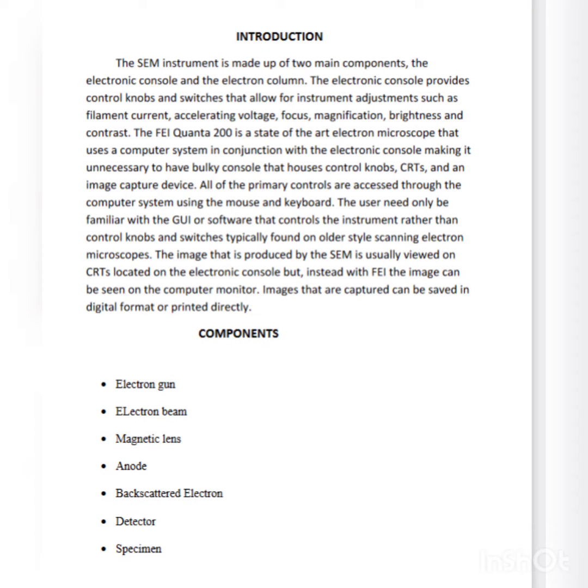The scanning electron microscope instrument is made up of two main components, the electronic consoles and the electronic column. The electronic consoles provide control knobs and switches that allow for instrument adjustments such as filament current, accelerating voltage, focus, magnification, brightness, and contrast. The FEI Quanta 200 is a state-of-the-art electron microscope that uses a computer system in conjunction